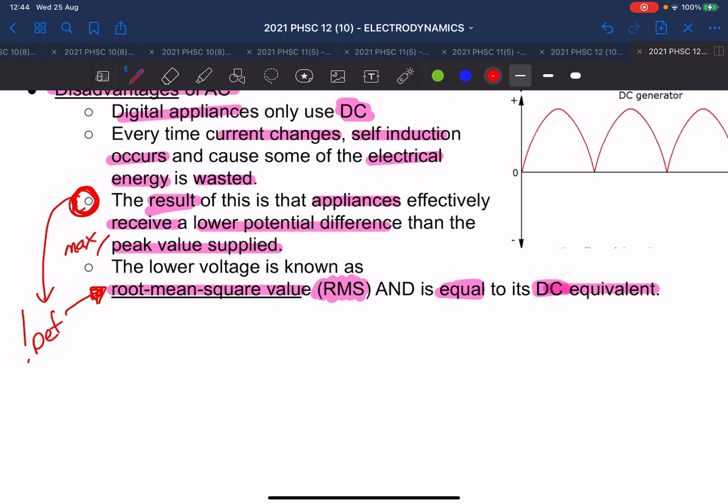But this here, we're producing current. Where else do we find currents? In circuits. So you can link these formulas with these formulas. Okay, so current formulas you can link with alternating current formulas. But very, very, very important. When you use the electrical or the circuit formulas, you must use the root mean square value. Okay, so here you're not allowed to use the maximum volts or the maximum current or whatever. It must be that lower one after self-induction has taken place.